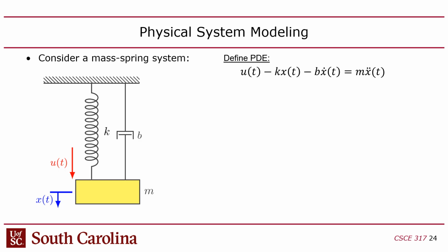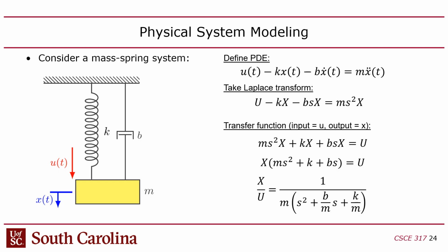And so you have to add a damper term. The damper is a third term on the left-hand side of this equation, and the damper constant is B. Basically that is also a negative term, but the damping is relative to the velocity. So it's equivalent to the friction of the coin dragging across the ground like I showed in the previous example. When you add that damper term and you solve it, you end up with another transfer function. In this case, the poles are all negative. Just by adding that damper, you end up with negative poles. So it becomes a stable system.